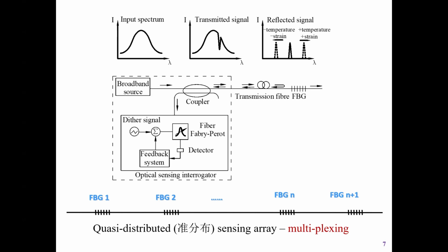For example, for vibrating wire strain gauges or for LVDT, one sensor needs one cable, 10 sensors need 10 cables. So a bunch of cables, you know what I mean? But here, with just one tiny, very small diameter fiber, we can measure multiple points. So it's very efficient, very compact, small size. Okay, so it's just a difference.